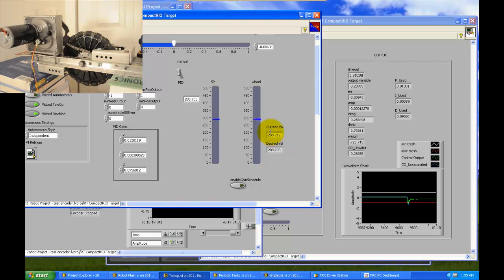And we look at our current value. Right now, our acceptable error difference is 0. What that means is we're telling the PID controller that the current value and the desired value have to have an error of 0. So there's no tolerable steady state error.